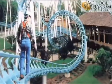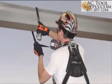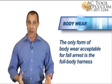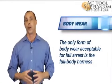Some anchorage connectors are built into connecting devices. These tie-back anchorage connecting devices will be addressed in detail later. The only form of body wear acceptable for fall arrest is the full body harness.